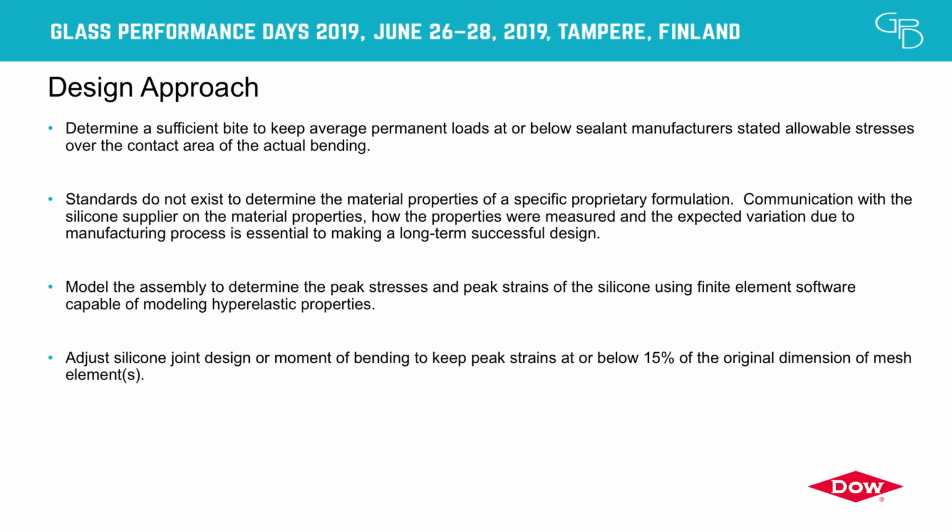So I think what this concluded is that we now have a little bit more of a robust design process, and are able to incorporate FE up in the front end of it, versus kind of a post-production step to see maybe what the stress distribution is for the cold bending using a mechanical method. In the paper we say keep strains at or below 15%. The IAC building's at 20, so maybe over time as we gather more data on the performance of that, it'll get to 20. But at least it's a start, right? I mean, it's perhaps a better predictor than what we've had in the past. That's the end of the presentation.